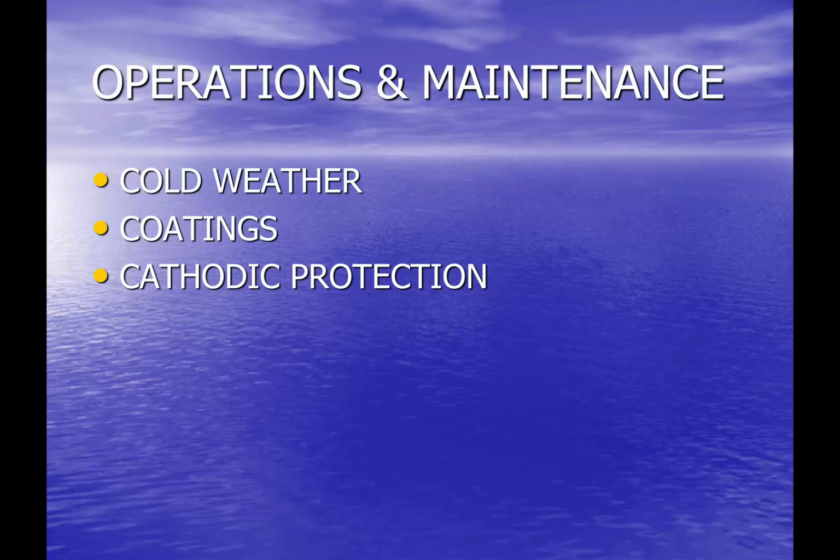Of course, anytime you're using sacrificial anodes, as we've talked about before, you need to replace them as they wear, as they dissipate, as they're used up. They typically, in an environment like this, can probably, depending on the manufacturer, depending on the type, get you plus or minus somewhere around 10 years before they have to be replaced. So it's not like you're out there every few months replacing your anodes. But it's something to keep an eye on.